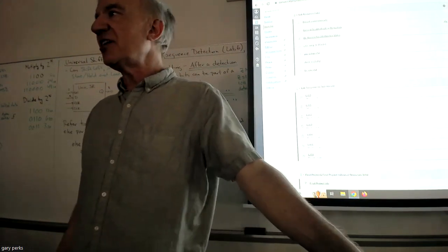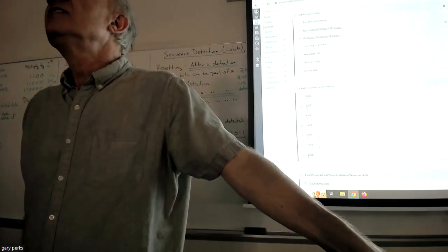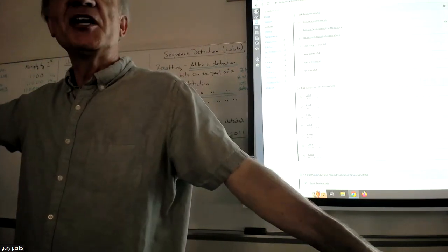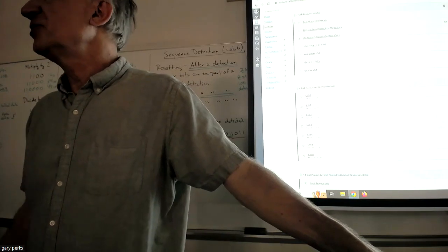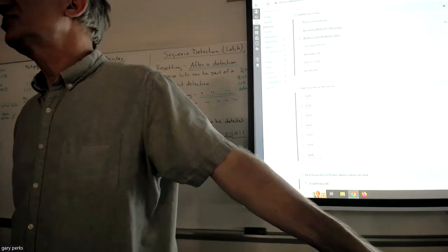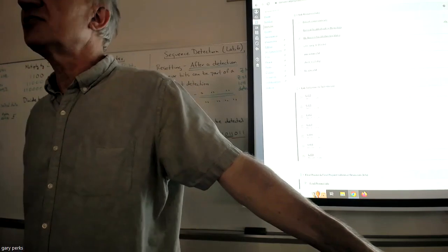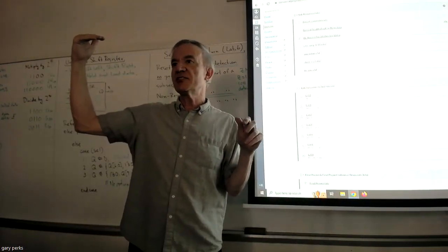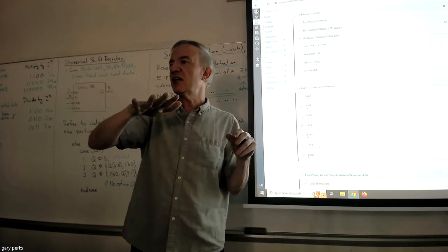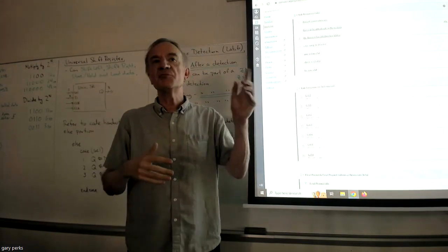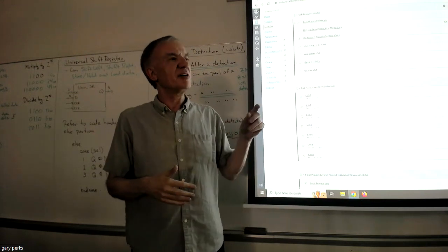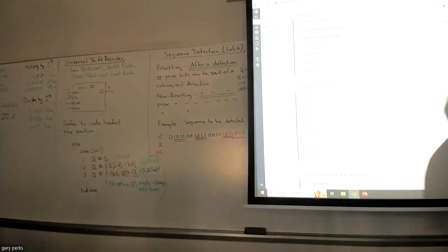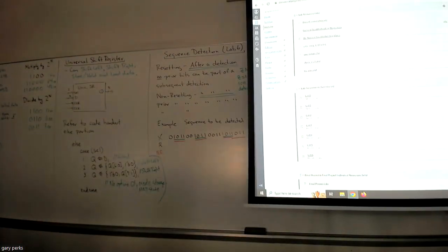Because we talked about a clock divider last class. What does a clock divider do? Like you put in the 100 megahertz into it, and what do you get out? A slower frequency, right? A slower clock. So that's exactly what this is doing. It's taking in the 100 megahertz from the board, and it's going to make it a lower frequency. But there is a modification you'll have to make that I'll talk about when I show you a video in just a moment.